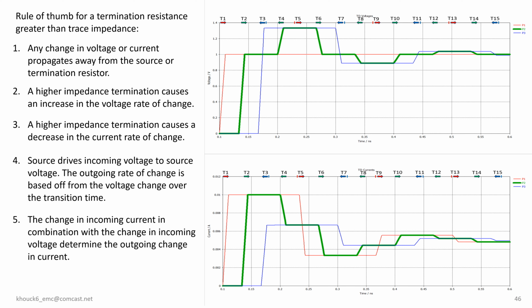Finally, the blue line represents measurements taken at the termination resistor, offering valuable insights into signal termination and reflection effects. At T1, the commencement of the changing field wave propagation is signaled by the drive, adhering to Rule 1. The current dependency is dictated by the trace impedance. At T2, the changing field waves traverse past the midpoint.